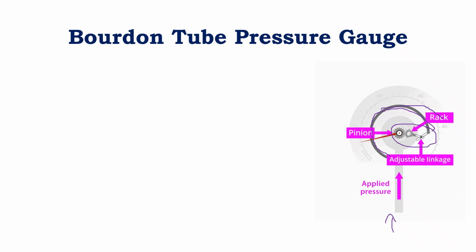It is attached to a lever system, a pulley-kind of lever system. Through this system, we get to know how much pressure is being applied from the bottom. If the pressure is very low, it expands very little and the needle only shows here. If the pressure is higher, the needle goes here. In the same way, we get a value using the Bourdon tube pressure gauge.